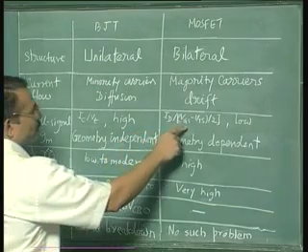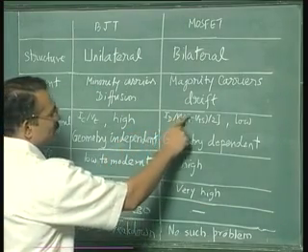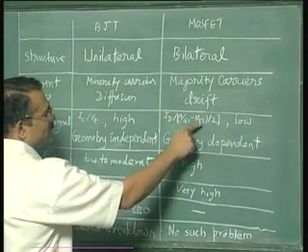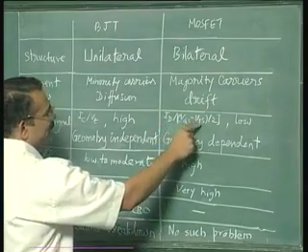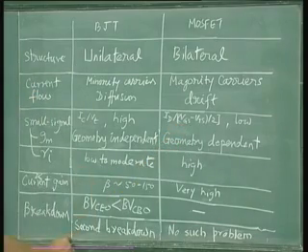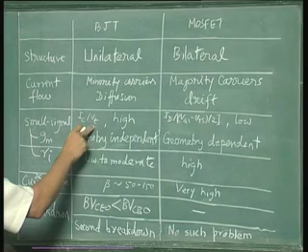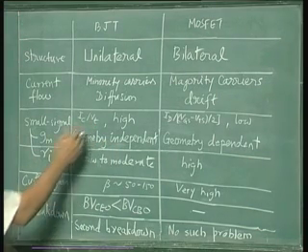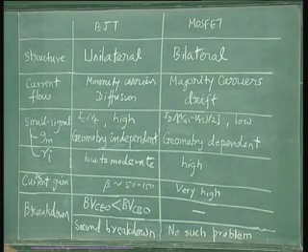Another property related to this GM is that this term here for the MOSFET depends on the geometry of the device. Threshold voltage depends on the geometry. Therefore, the value VGS minus VTS for any ID depends on the geometry. So the GM is geometry dependent in the MOSFET, whereas in the BJT this VT is independent of any geometry, a great advantage, and therefore it is geometry independent in the case of BJT. So high GM and geometry independent of the structure, great advantage for the BJT.